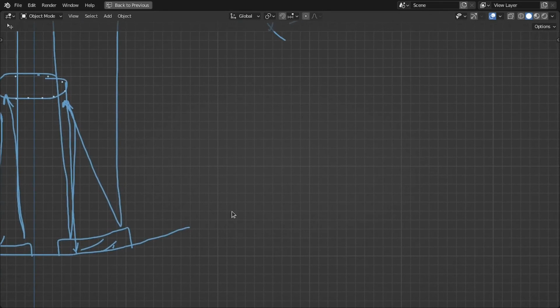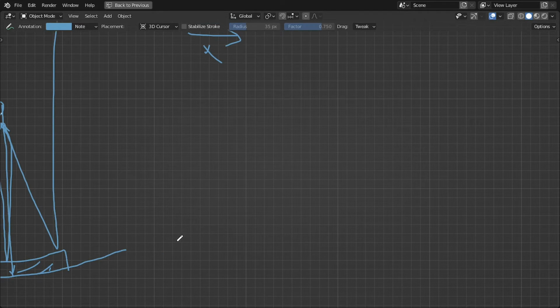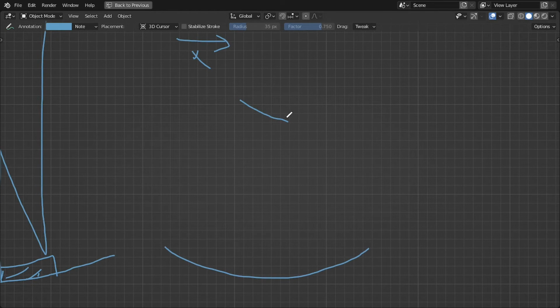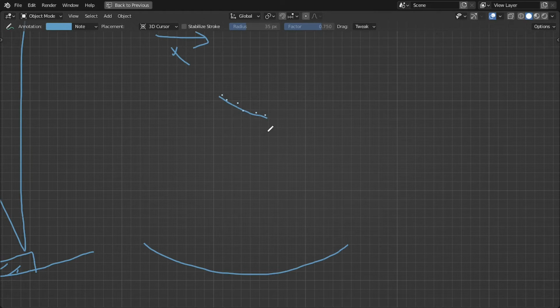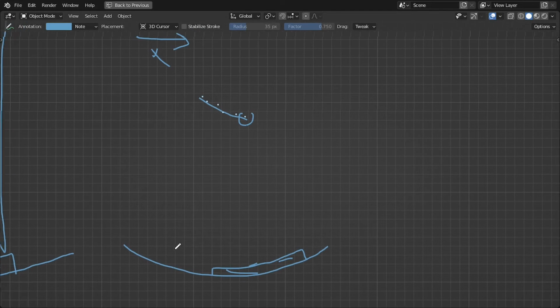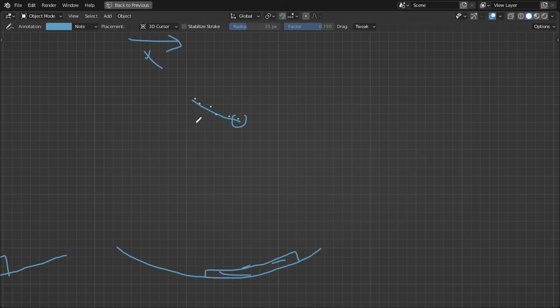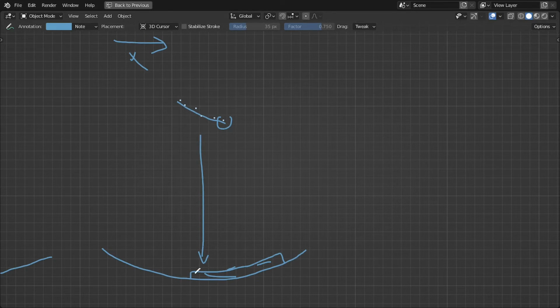Suppose our mesh is something like this, and this is the shape for the caustics, and if we scatter these points on this shape, this point is going to get more area on this surface because it is closer to this mesh, and these points get less area. So the best thing is we project these points onto this surface and then use the proximity node.